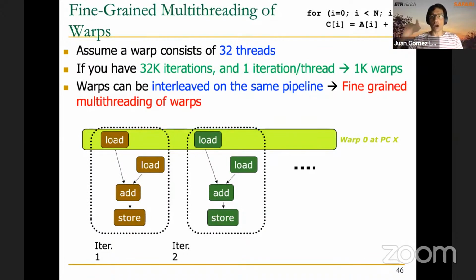Each of the warps behaves kind of like a vector thread, and has to execute a sequence of instructions. I was going to tell you how the GPU hardware internally creates these warps. Typically, we have a number of threads. Each of them has an ID: thread 0, thread 1, thread 2, thread 3, and so on.